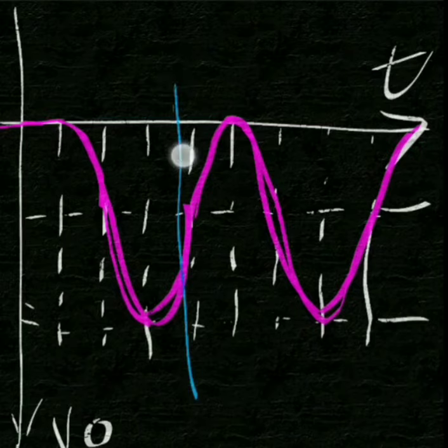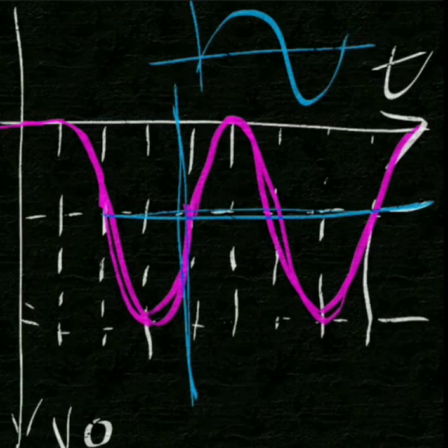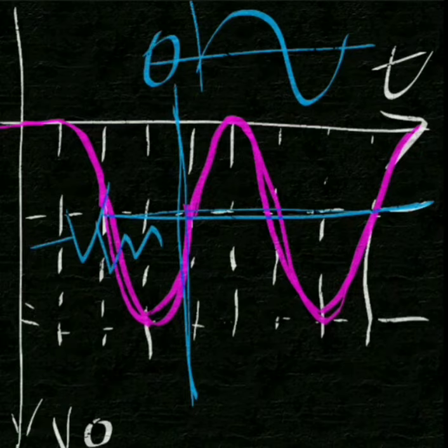So after this instant our input was this, so we can say here it was 0 and this is minus Vm. So we can say the signal has the same shape, but the only difference is the DC level has been shifted from 0 to minus Vm, that is towards the negative side, and hence this circuit is a negative clamper circuit.